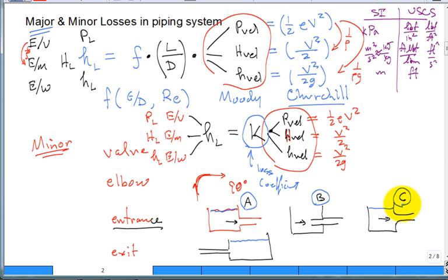When I teach fluids, I usually talk about just following a little pack of fluid. It's easy to go straight in, but you have to bend around here, and that sharp edge sometimes has a little recirculation region. That's why it's a larger loss than if it's smooth to help make that turn. Just think about little fluid packets. But when you come here, some fluid packet is eventually going to have a really wild turn. So the probability of having a greater degree of separation, hence more loss for the protruding pipe, is why you have a larger loss coefficient.